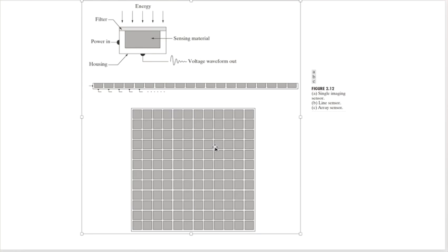So the whole purpose is you're trying to force it so that gap. Remember, you take the P and N material. The P has positive charge carriers. The N has the negative charge carriers. Put positive and negative together, what happens? They mix up and they're gone, right? So you get this depletion zone. You put the P and N together, and right at the boundary zone, they cancel each other out. So nothing can flow because there's no charge carriers. It's a big dead zone. If you reverse bias, you cause that dead zone to get bigger.